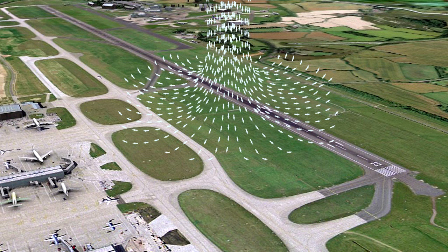A microburst is a column of air descending very rapidly at speeds of up to 250 km per hour, which, upon impact with the ground, spreads out in all directions. The descending column of air may or may not be accompanied by rain. The microburst is the single most hazardous weather phenomena to aeroplanes close to the ground, when they are either in the takeoff or landing phase of flight.